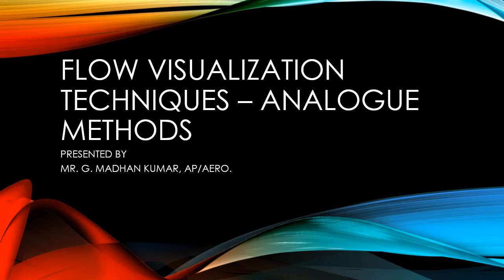In today's class, we are going to discuss flow visualization techniques, analog methods. Basically, what is meant by analog methods? It is the method used for solving fluid flow problems by setting up another physical system. You need a second domain physical system, and with its help you are going to visualize or calculate some of the fluid flow properties. After checking those fluid flow properties, you are going to match them with flow visualization properties, right? So this is basically called analog methods.